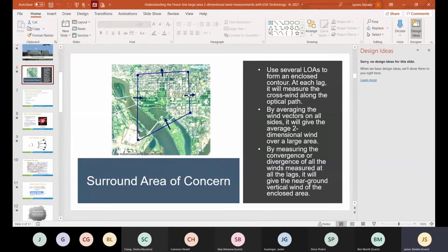the wind is doing, because like I was mentioning before, if you have a wind gust, you can have a wind gust through one part of this, but maybe it's not all the way across. So if you have an anemometer there, it may say it's blowing this way, and you may get a higher concentration with a single-point concentration analyzer. But with this, you're getting an average wind across that whole area. So you're like, okay, this is how much wind and how much of that pollution is going across that whole